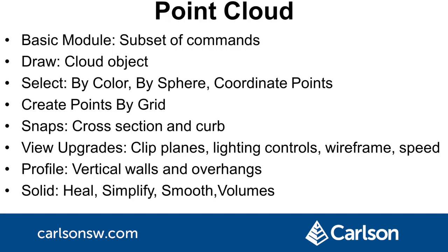For drawing the cloud to CAD, there is a new method to create a point cloud object, which allows for viewing and snapping to large clouds in the drawing. There are new ways to select, including select by color, by within sphere at pick point, and controls whether to select cloud, solid, or coordinate points. There is a new function to create coordinate points at a grid interval. There are new snaps for cross sections and curves.